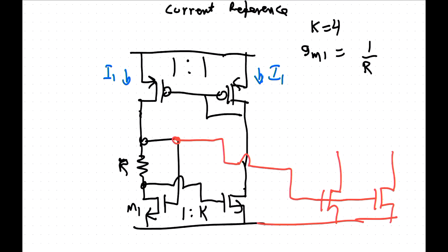You can either put this off chip as a reference resistor. That's perfectly fine. Your op-amp didn't have an off-chip resistor, I don't think, because that would be annoying. So you can do it, and for a test circuit it's good, but for production, your manager would not be happy if you say, I need an off-chip resistor. You might be out of a job.